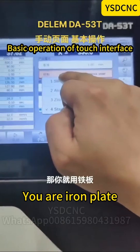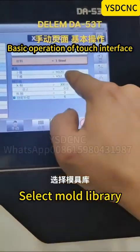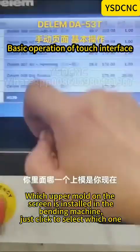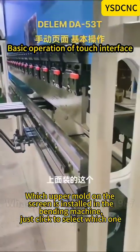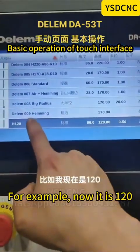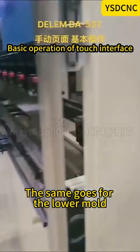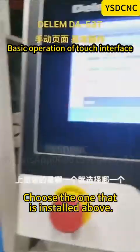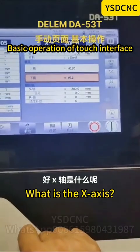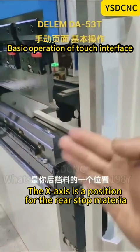If you are using iron plate, then you select the upper and lower modes. Select mode library. Let's click it. Which upper mode is installed in the bending machine on the screen? Just click to select which one. For example, now it is 120. The same goes for the lower mode. Choose the one that is installed above. For example, V12. What is the x-axis? The x-axis is a position for the rear stop material.